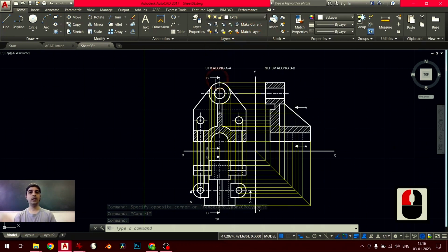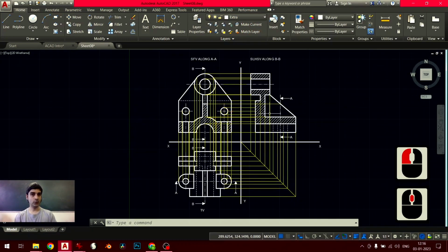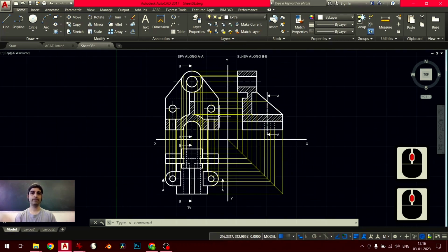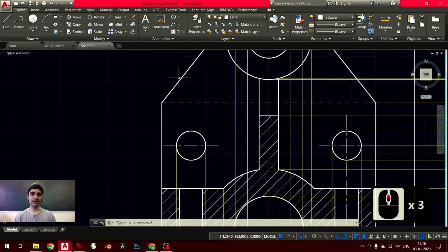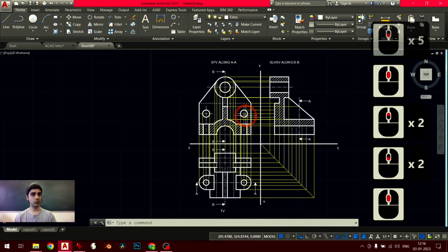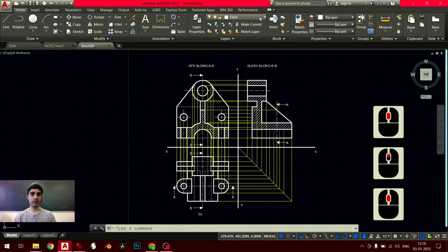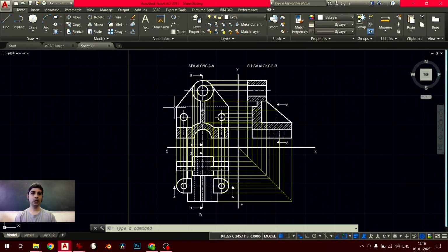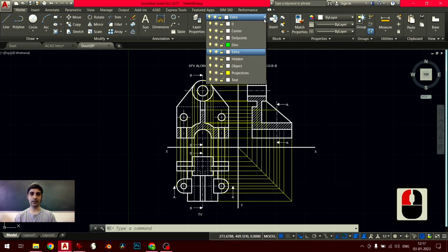All right. Now, layers can also be very useful if you know how to use them. In this file, for example, I have layers set up for these thicker white lines and layers set up for these yellow lines and so on and so forth. So once I'm done with my drawing, if I only want to see these white line objects and I don't want to see any of these yellow lines, right? I can open this little drop down and this light bulb next to each of these layers turns them on or off from the display.